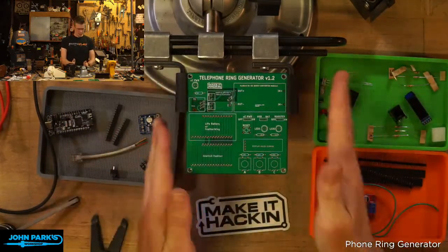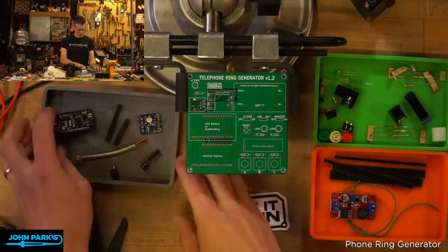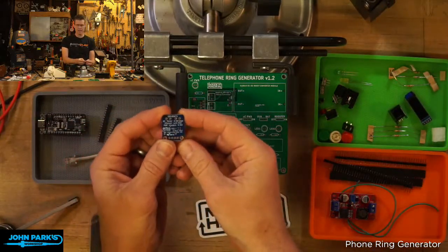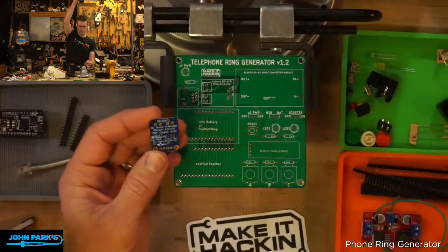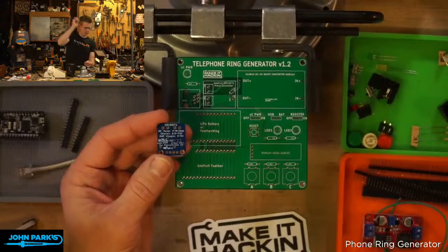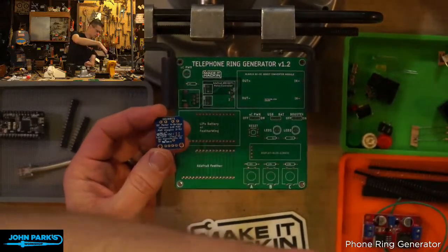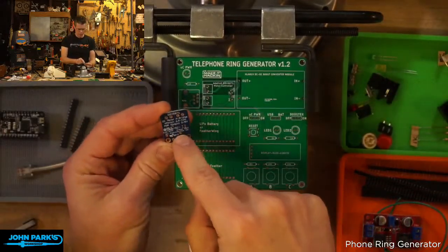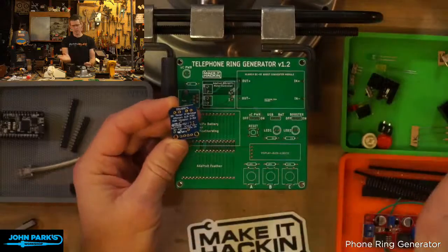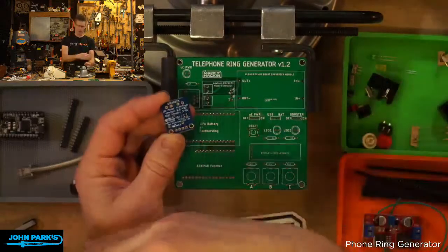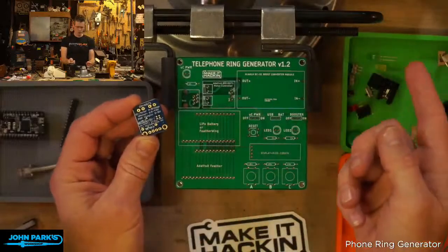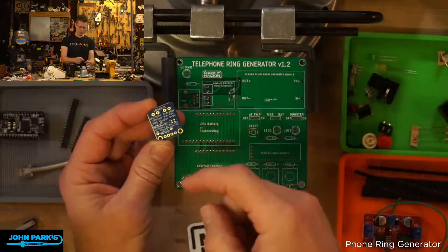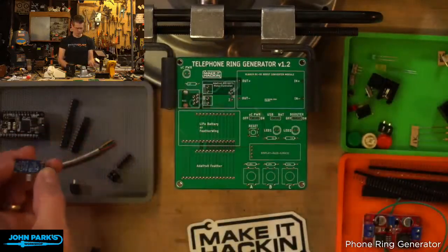Okay, so here's our bill of materials. I have a feather. I have our motor controller. This is the DRV8871. This is an H-bridge motor controller, so it can send essentially in two directions the sine wave that we need to control the ringer. Normally this would be used to drive a DC motor forward or backwards, but this is going to be used to generate that sine wave that rings the bells.